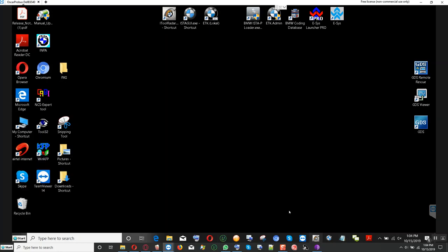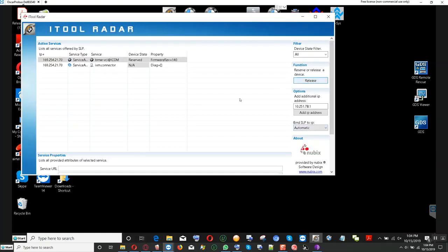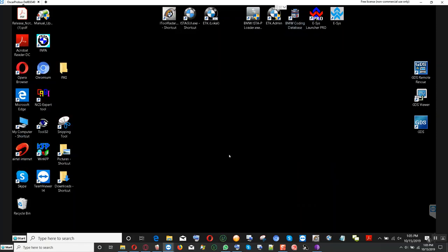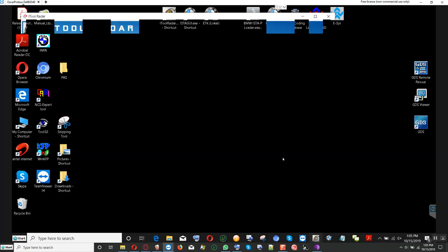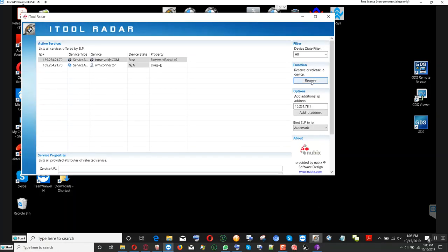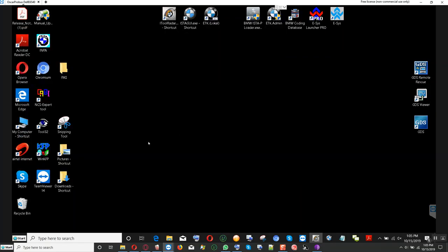We release the icon. Oh, the DME has to be coded with NCS Expert. Okay. We close back the icon. We're gonna lock it back. We have to code the DME now with the NCS Expert.